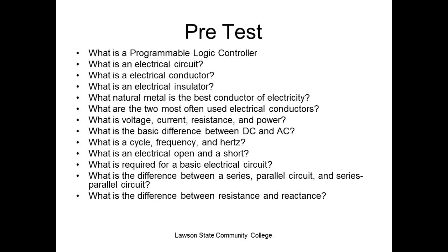What's the difference between series and parallel circuits? Everybody's had DC in here, right? So what's the same in a series circuit? Current. So current's the same through each circuit unless something changes in the circuit. Y'all probably saw that test on DC where they said, I changed this resistor, and people say, well, nothing changes because current is the same in a series circuit. It's not the same if you change something in the circuit, right? It'll be the same in that circuit, but it varies depending on the components. Parallel? Voltage is the same. Yeah, the voltage is the same in all your loads inside the circuit.